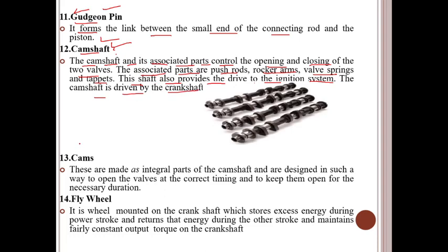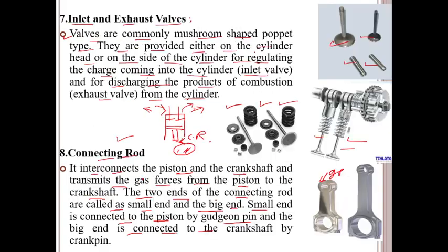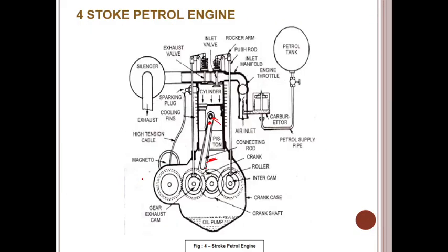Now another, these are the cams. They are made as integral parts of the camshaft and are designed in such a way as to open the valves at the correct timing and to keep them open for the necessary durations. So this is the cam. You observe here in the diagram, there is a connection of the cam.